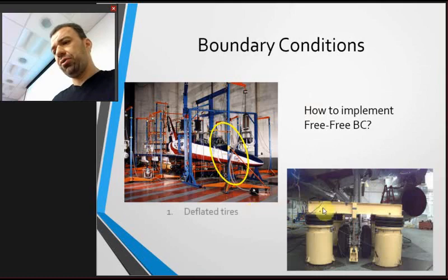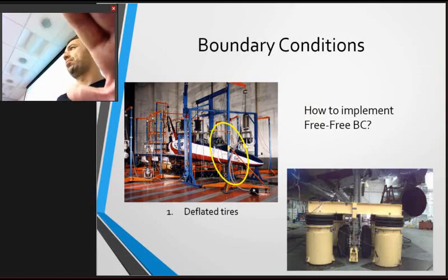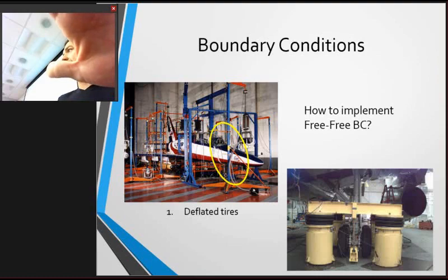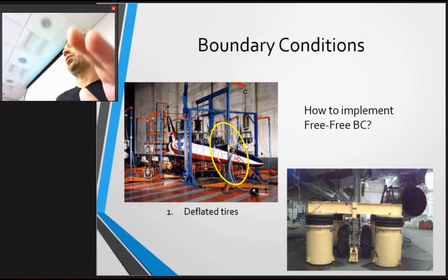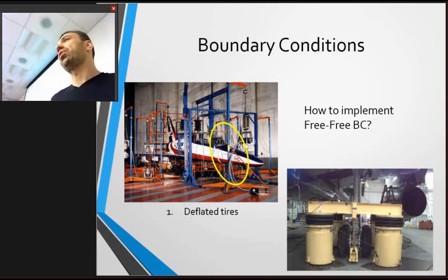Okay. First of all, you deflate the tires. What this achieves is essentially you're having a soft pillow for your plane to stand on, and the frequency of the plane on the deflated tires will be low enough to not interfere with the elastic modes and frequencies.